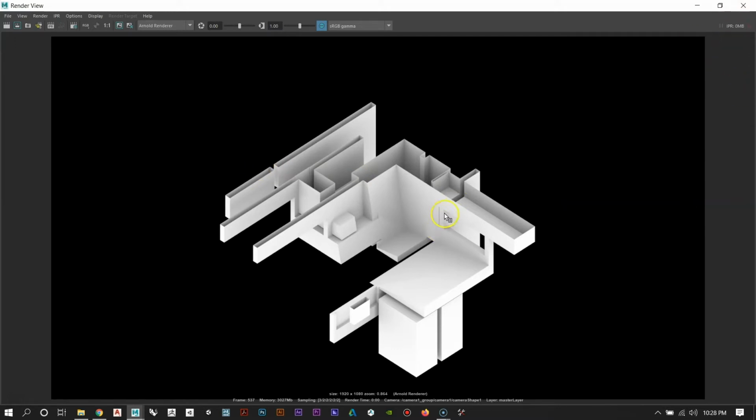And this looks fine, I've got no problem with the way this looks, but there are two other options. We can either infill all of this with poche, so it actually looks like you're cutting through a solid piece of material, or we can give thickness to it and then cut it, and it'll look like you're cutting through an actual wall. So we'll get into those next.